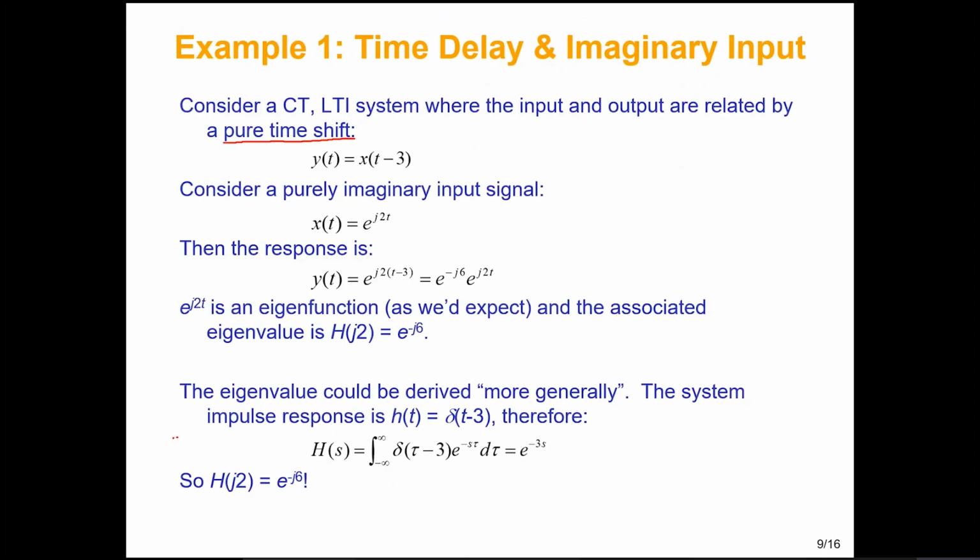Okay. So the same thing is actually covered right here. If we are given a pure time shift system which has a difference equation given to us, and if the input is e raised to the power of j2t. The example I did was for e raised to the power of minus j2t, so it is the same thing; you can just have this example here. If the input is e raised to the power of j2t, we can directly find the answer just by replacing x(t) with e raised to the power of j2t. The output can be directly found out to be equal to this, and this is for plus j2t. Output is this. Now we need to find h of s.